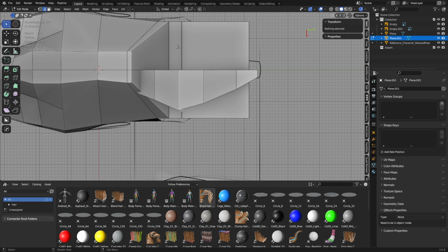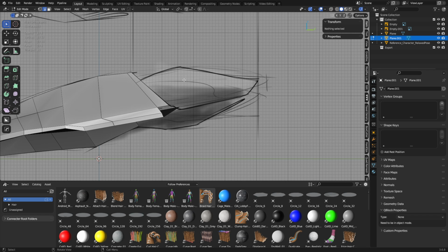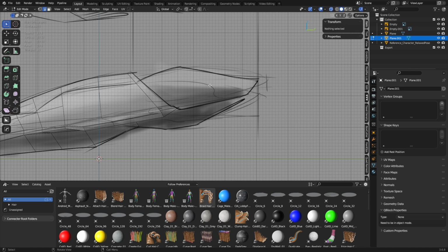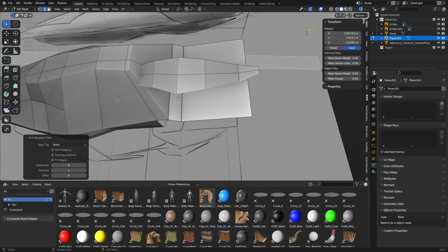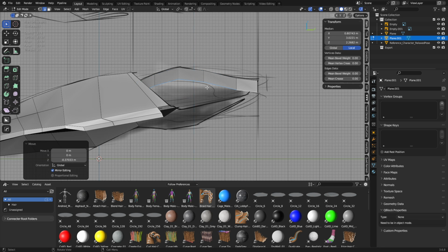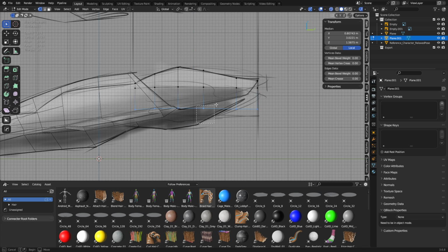And so you can see this is actually the side edge here, and the middle's all right. So we'll do a loop cut here. We'll pull all these ones down. This is going to flatten, so S and Z, you can flatten it. Potentially pull that down more. It looks like it might become a solid piece all the way through, but this is where taking your time sketching, solving these issues would definitely go a long way.